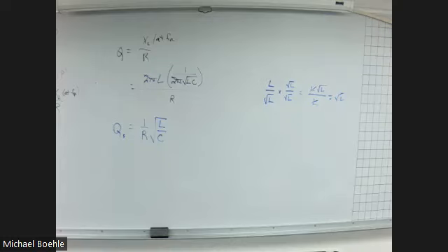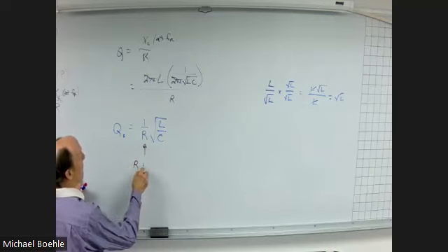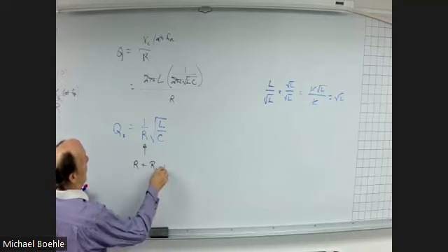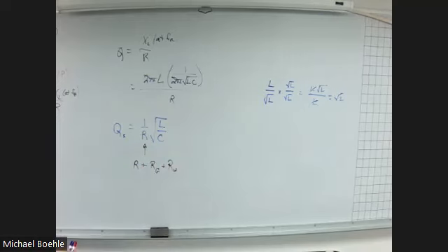So when I go and look at this resistance here, the Q of the circuit is going to depend on whatever physical resistor you put in, plus the generator resistance, plus the winding resistance of your inductor. It all adds up. And as it adds up, what happens to the Q of the circuit? It goes down.